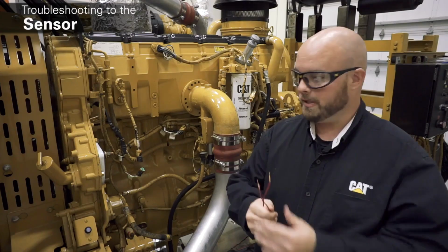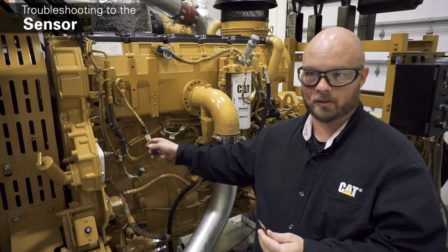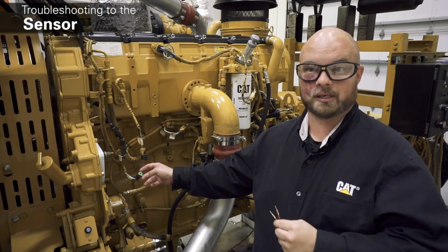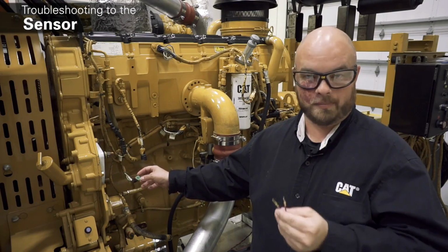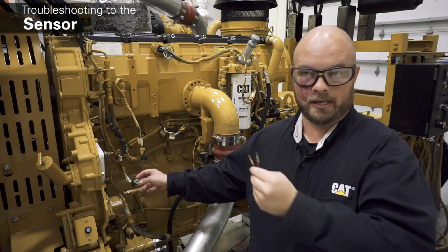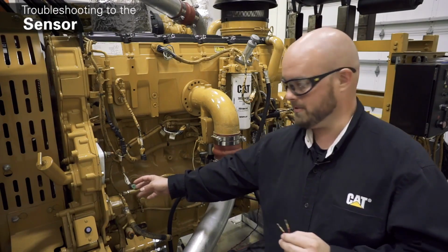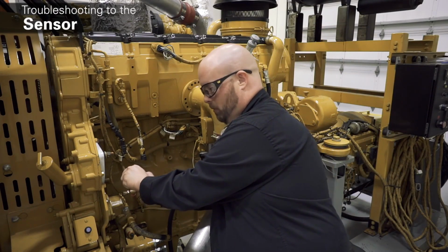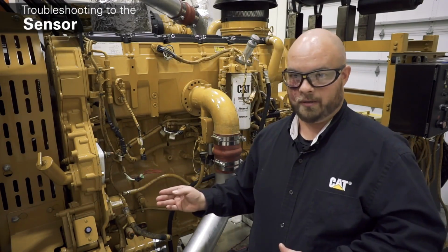And what we're gonna do is, with the sensor out of the equation, he's not in play here at all, we're gonna take that signal wire, the C wire, and short it by applying the sensor ground, the B wire that we already validated, and cause a short circuit between B and C and see what happens. So we've got the B ground wire and the C, the signal wire. Now we wait.